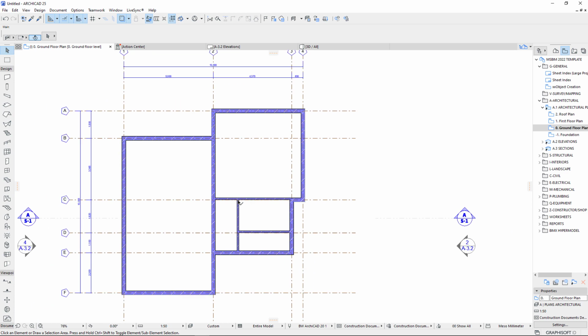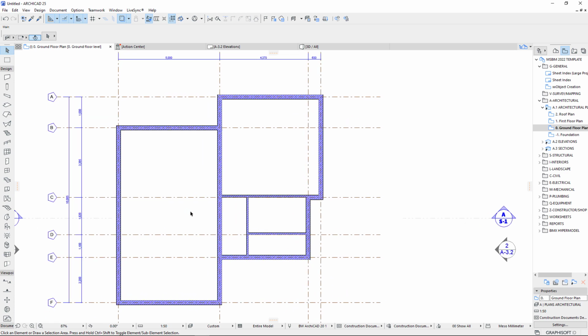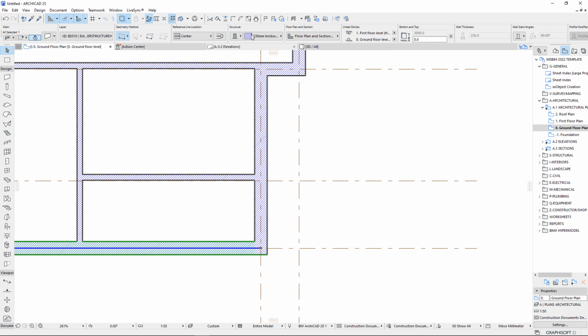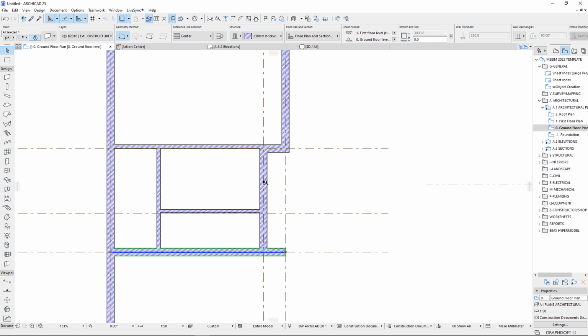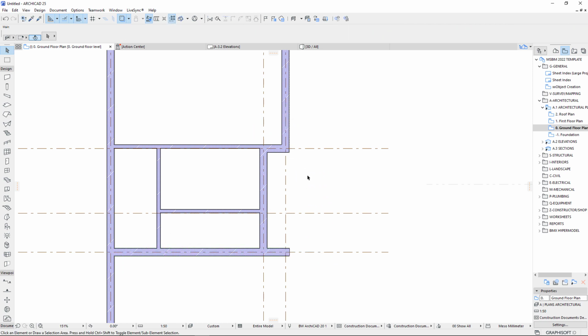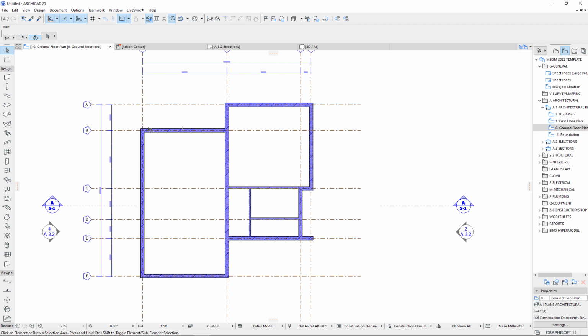So what I'll do, I'll move on and place the openings for this project. As you can see, I'm very impressed with the overall thing now. With that, I think this wall, let me extend it to here, to this grid, because this is a duct for the plumbing pipes for both the bathroom and the toilet. So let's just stretch it to here. Perfect. So let's go for the openings.